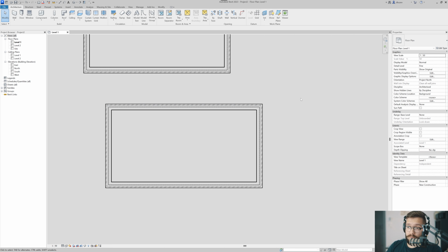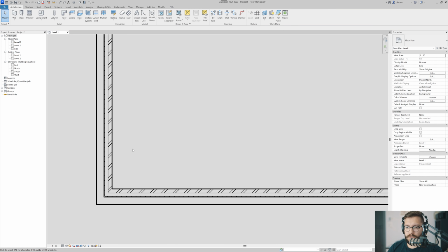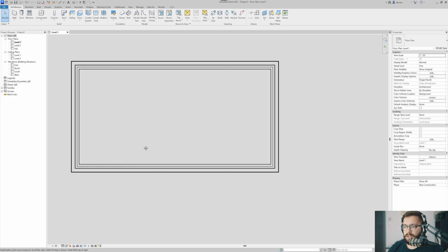Great way to do this very, very quickly is to select one or all of the walls that you want and hit spacebar. This is almost another truism in Revit, that anytime you want to flip something, and this is almost every time, so not all the time, you hit space and it would reverse it. Sometimes it would flip it actually in 4 different directions, depending on how this particular element is created.